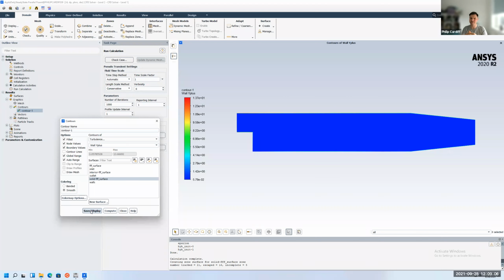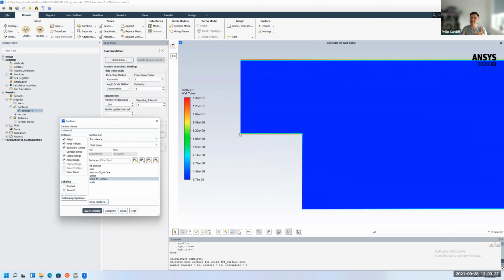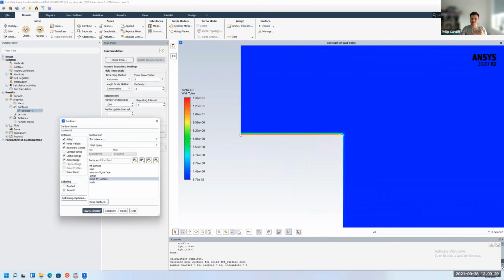So this Y plus is basically like a normalization. It's kind of like a mini Reynolds number. It's taking the Y and normalizing it with respect to the energy of the incoming flow, the kinetic energy. So it means that we can use this Y plus to compare different geometries with different Reynolds numbers, and it still works. So Y plus is like a dimensionless measure of how far away the first cell center is from the wall.